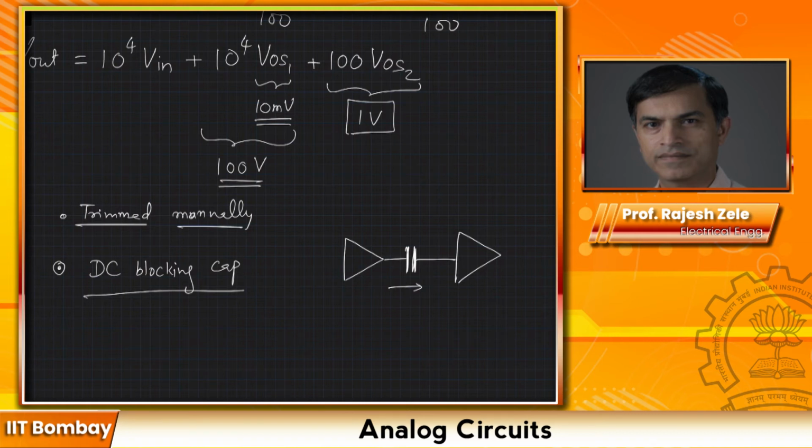So I'm giving you a really elementary or rudimentary explanation, and all this stuff we're going to go through in detail as we dig into the devices. But just the concept is the capacitor does not allow DC to go through. The important caveat here is that your signal content should not contain DC, because otherwise the signal will also get blocked.